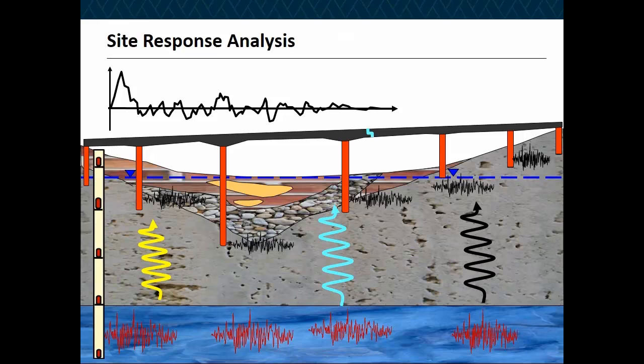So let me tell you what happens when you look at a seismic analysis of these long span bridges, and what are the steps and process that you have to go through in order to analyze these types of structures. First, when you have these long span structures, obviously the ground motion at every support is going to be different. So first, engineering seismologists will develop a rock motion at every support. The motion will be propagated using site response, coming to the foundation level from the geotechnical engineer. So far, the rock motion will be done by the seismologist.